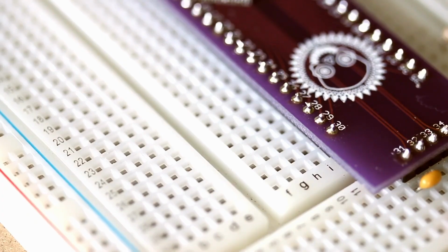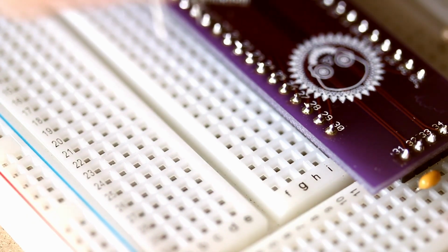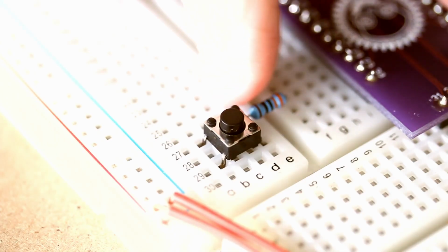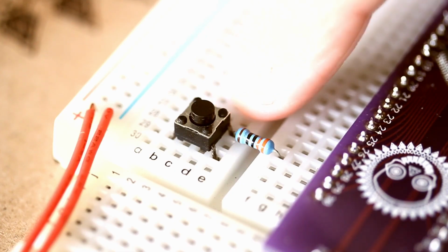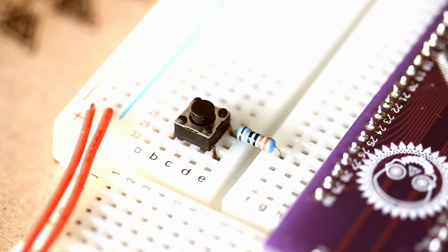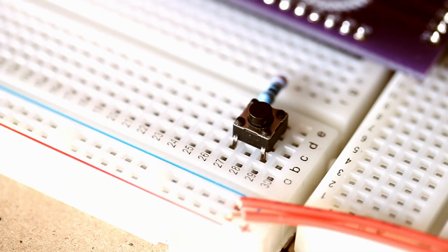Now we can connect the switch to pin number 27, which is port B, pin 1. We'll start with the 330 ohm resistor, connecting the two tie strips. Then we'll put the switch, allowing the lead of the switch in the back here to share one of the spots in the tie strip with the resistor. So it can give me enough room back here to put the other resistor. And we'll put the 220 ohm resistor on that same tie strip to ground.